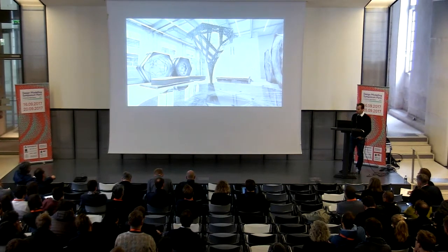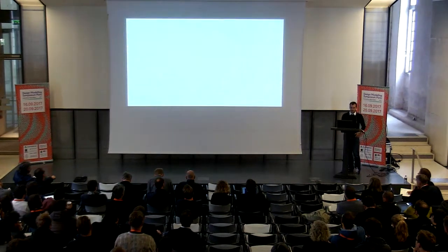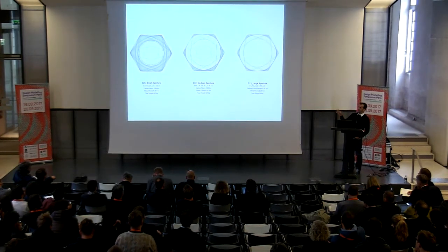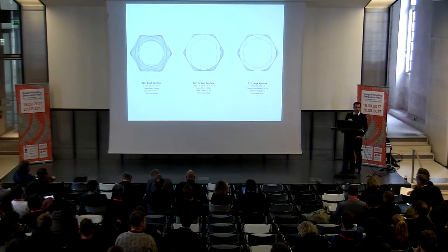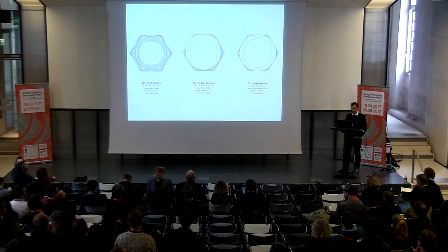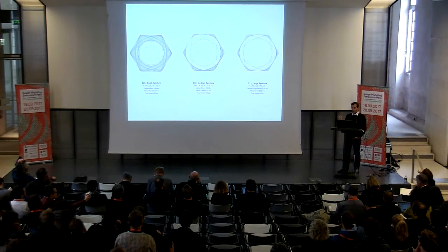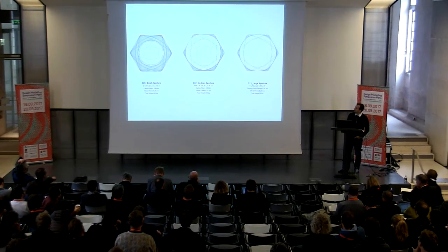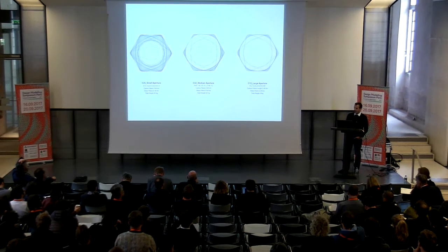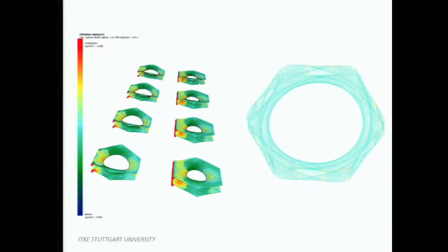So with one tool that can be collapsed and is obviously removed after the fiber is cured, that's important to say, we can build an infinite number of differentiated, finely calibrated to the actual force requirements set of components. So this is done by having a direct feedback between the structural analysis, which happens on the one hand on a shell level, on the other on the actual level of the fibers.